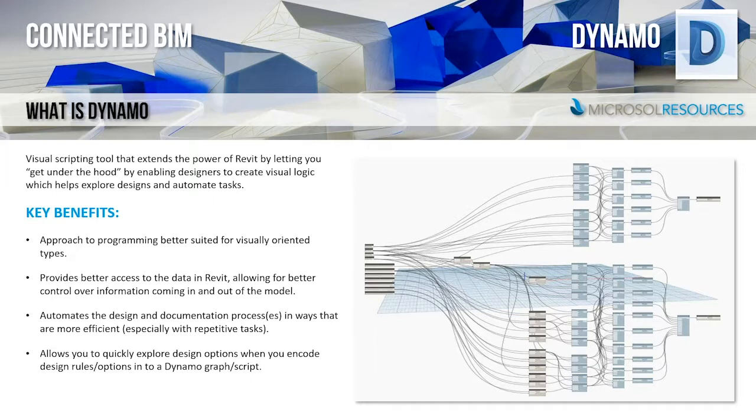There's a lot that we do that is repetitive in Revit. Doing something in Revit is pretty simple, but doing it over and over and over again, 10, 20, 50 times, can take up quite a bit of time. However, Dynamo can help us with that. Some examples of this would be renumbering a sequence of sheets, flipping grid heads, batch inserting families, changing text from uppercase to lowercase or vice versa, and importing and exporting data to and from Excel.